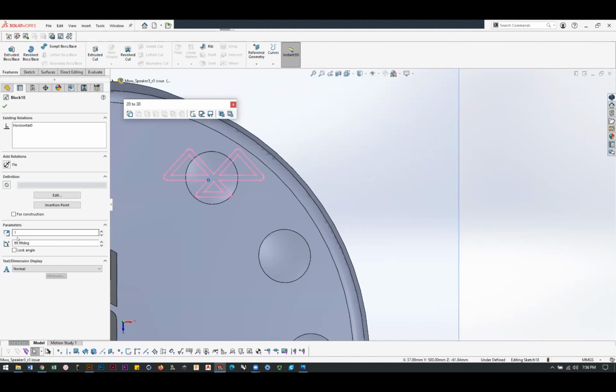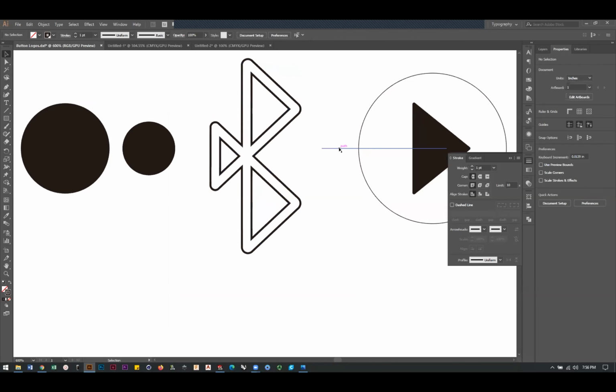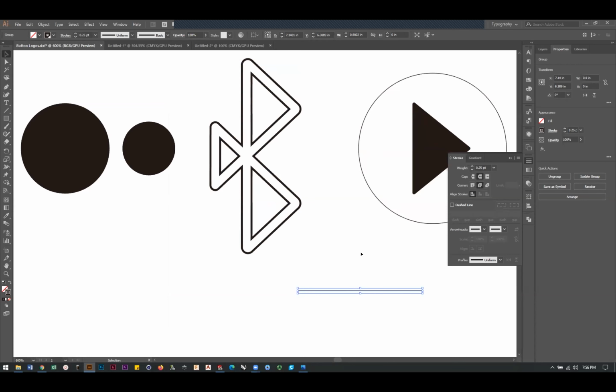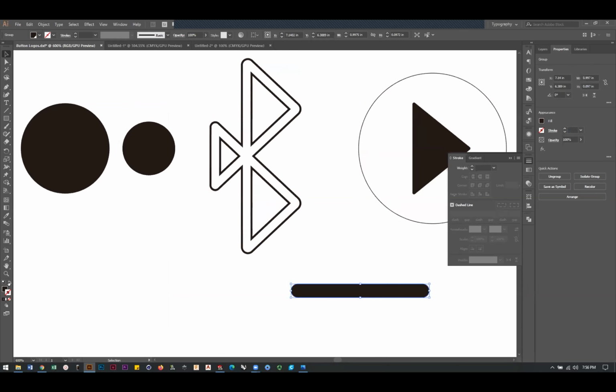Yes. Well, that sounds like part of the issue is back here in Illustrator. You've got to take your line work like that and put a big, thick outline on it. Then do this trick where you go to Object, Path, and outline the stroke. That'll give you the outline of the single line.